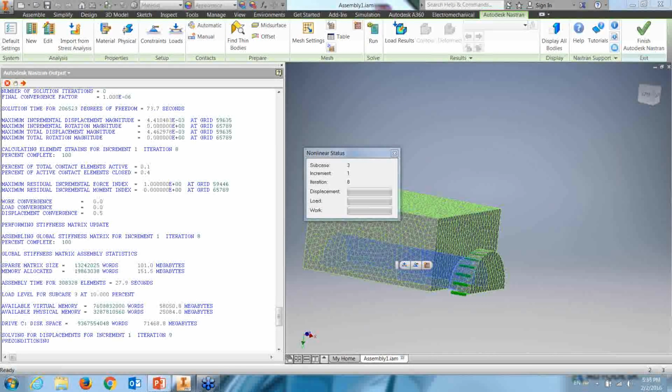There are some situations where you don't want the symmetric contact. If you've got sliding, like a buckle and a backpack that snaps together, in that instance you're probably going to want an unsymmetric contact. Or maybe two cylinders, a pin within a hole, similar to the situation we have here, but where the pin is actually rotating.